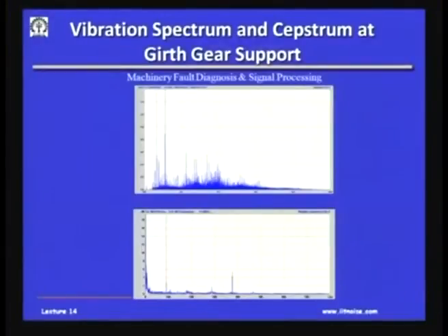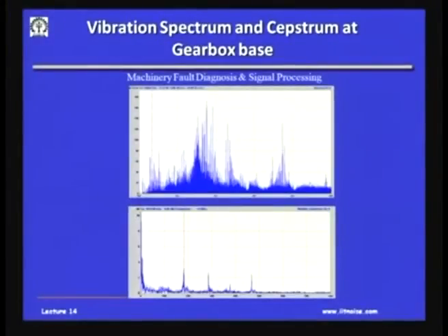Now, if I come back to my example here, again look at the vibration spectrum and cepstrum at the gearbox base. If you just compare the gearbox base, because of a very poor foundation, you see so many frequencies coming up in the spectrum, and if I asked anyone to find out the frequencies contained in the signal, you would all be scratching your heads, getting lost, wondering what the frequencies are here.